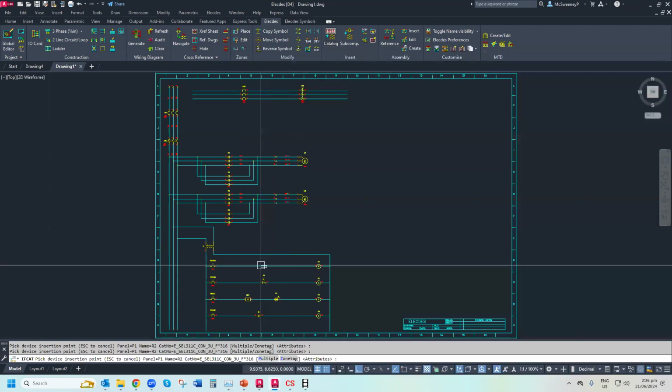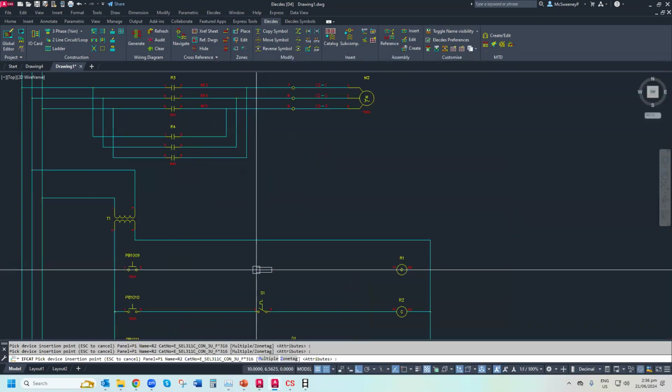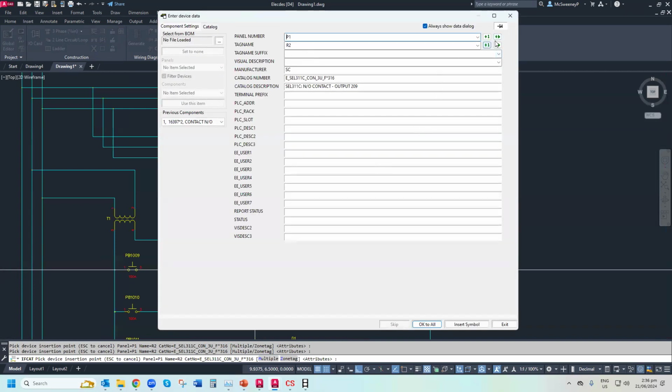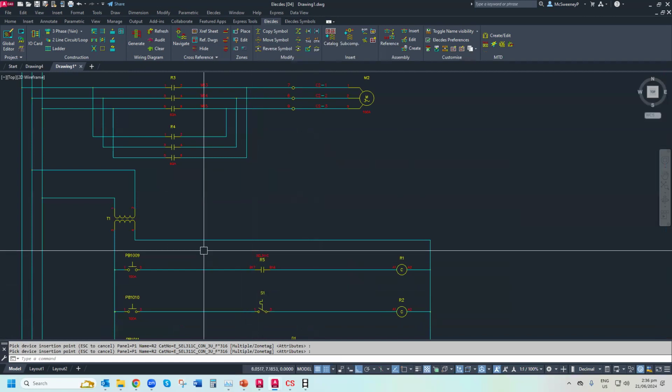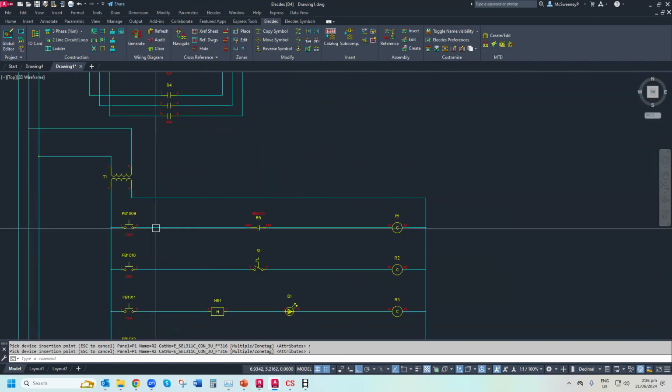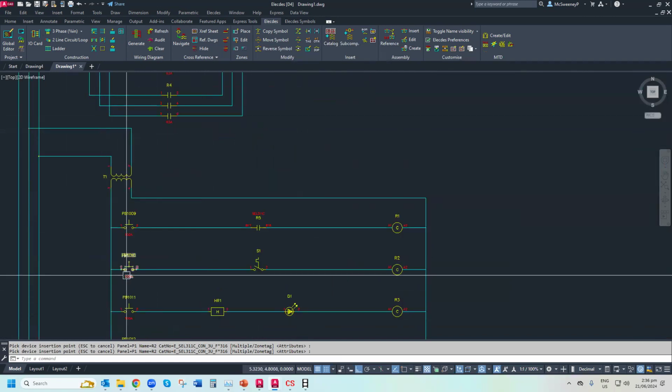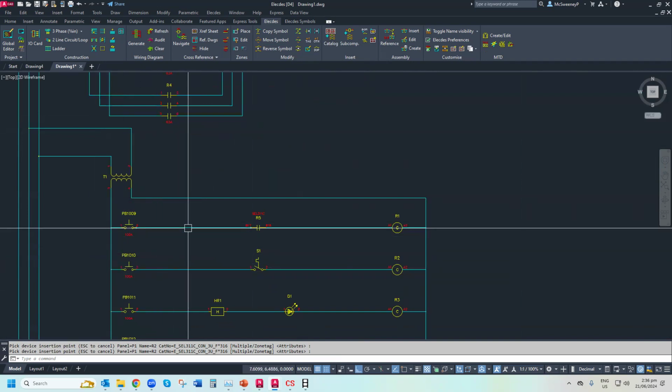Now what I can do here, again, I just zoom and line it up. But the important thing is I can just go next available because I've already got 4 relays. So it'll jump straight up to R5. Okay to that. Now the other thing I do in here is I put in some discrete wire numberings, but not on all of them. The key point, which I don't know if I actually mentioned before, is we keep it simple.